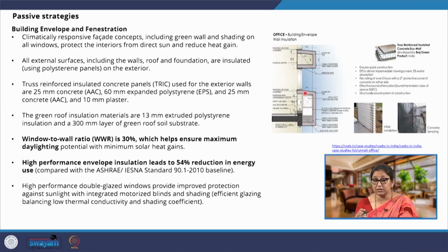And what is happening? The HVAC ducts are running through this cavity that has been created. So, this cavity protects the indoor spaces from receiving a lot of heat. This window gets a continuous projection, it remains shaded for most of the time, it cuts off the direct radiation, but allows the penetration of sufficient daylight, because it is like a continuous window that has been provided.